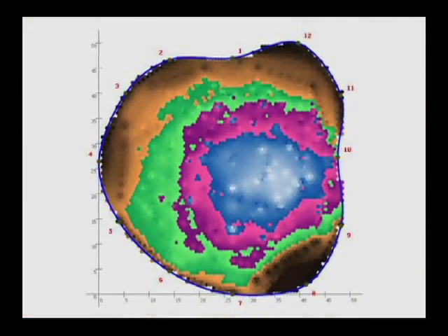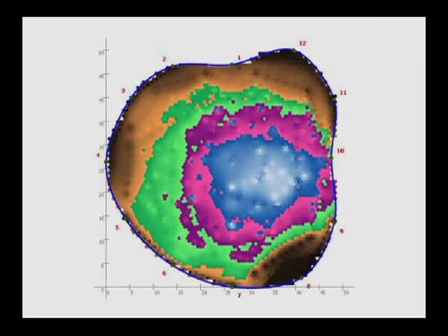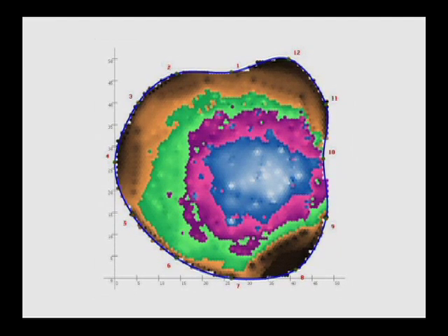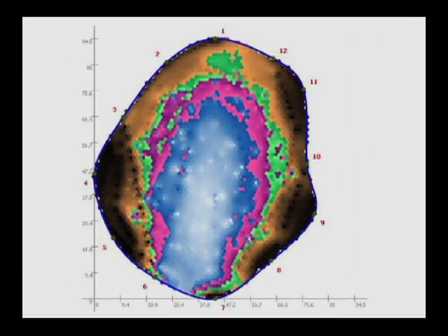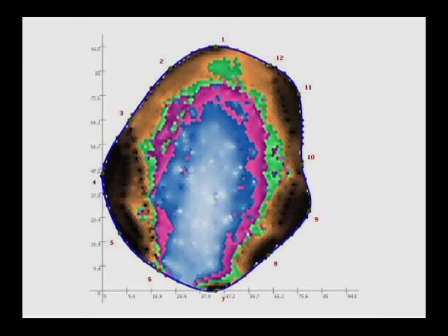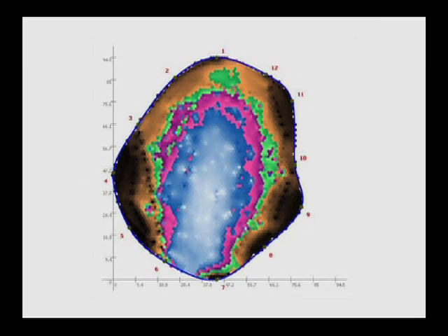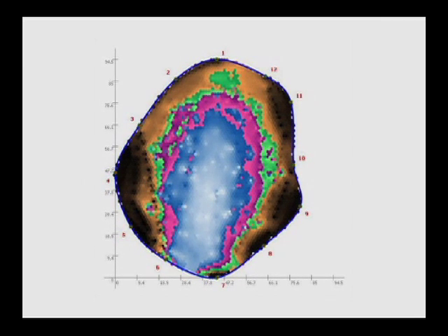Computer projection software using stress wave data from multi-path measurements creates an image of the distribution of relative sound wave velocity in the cross-section. The tomogram in this example is displayed in 4 colors representing varying recorded velocities. Velocities are displayed from low to high as blue, violet, green, and brown. This map of the acoustic characteristics of the sample cross-section, with accurate interpretation, can determine the size and location of internal trunk decay and defect.